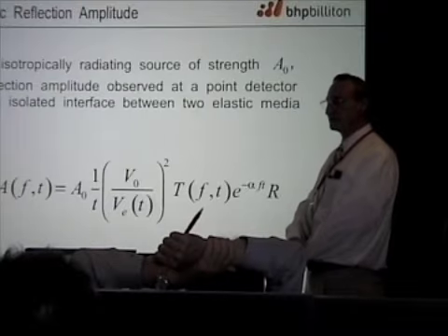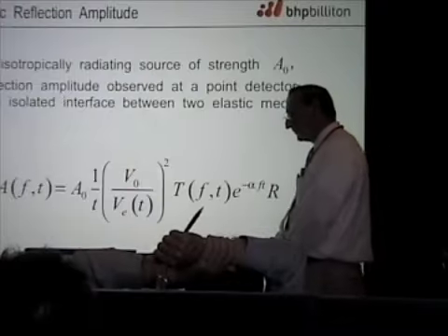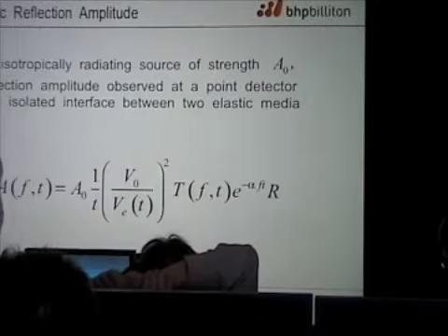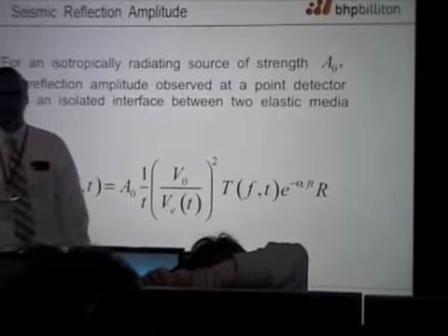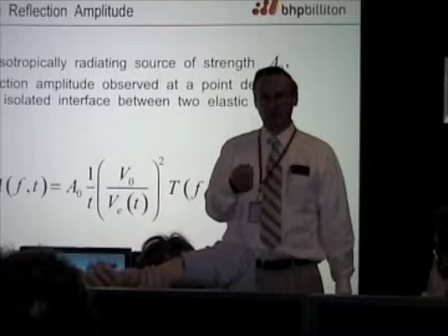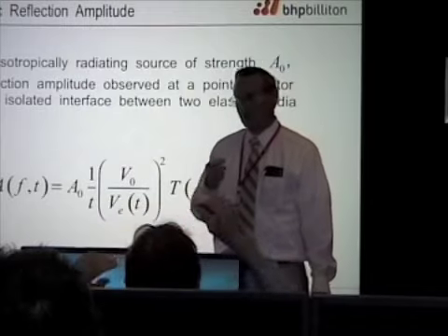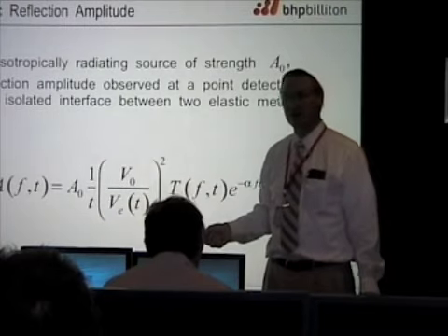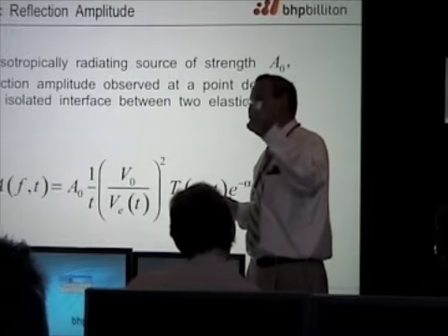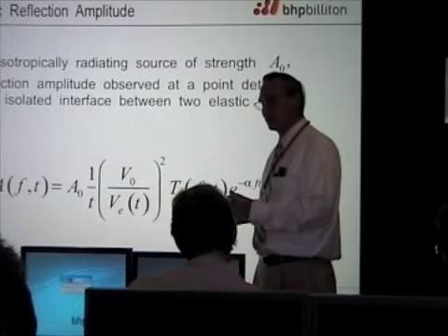1/3000th of the energy in the source is what's coming back. That signal is really weak. You're familiar with this if you have a little handheld microphone, which has an automatic gain ranger, so that if I'm close and I talk at that thing, and then we play the tape, you'll hear it. But if I keep my mouth shut and there's a choir singing over there 100 feet away, you'll hear the choir, even though that signal is a lot weaker than my voice, because it'll automatically range gain up because it was quiet in between. And so it's got to boost the gain until the next signal comes in.